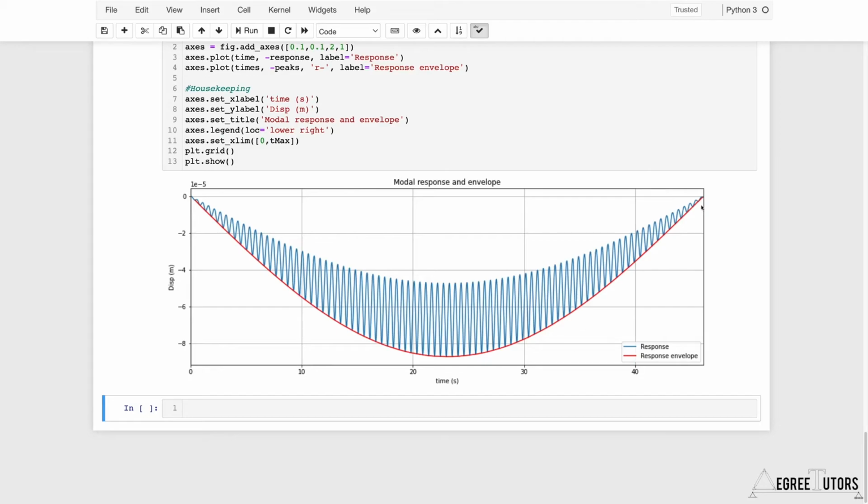So we're doing a simple toy case of it here, but you're going to get the idea. In our case, I'm going to consider the influence of bridge mass per unit length. You can imagine a scenario where you're at the early stages of designing a footbridge, and you might be thinking about what kind of construction or materials you're going to use, and that's going to have an implication on the weight of the deck, the weight of the overall bridge per meter run. There are going to be pedestrians walking across it, so you might want to get a feel for what the response is going to be for different weights of bridge deck. Let's say a very, very simplified case, but you get the idea.